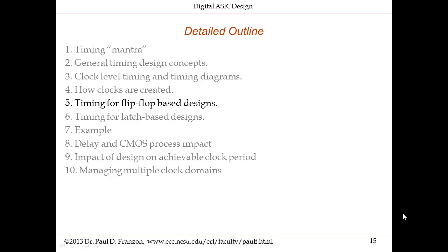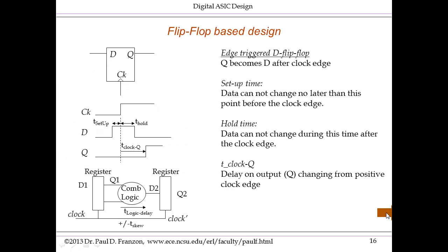But first, all we're going to do is talk about deriving the timing equations for setup and hold conditions for flip-flop based designs. To do that, we first will have to define setup and hold, and in fact all the major timings are related to edge-triggered flip-flops. Of course, the behavior of an edge-triggered flip-flop is the output Q becomes equal to D after the clock edge. However, there's some details in the timing that are very important in order to get working designs.